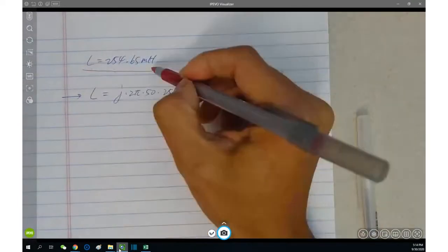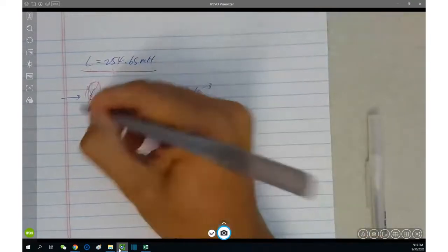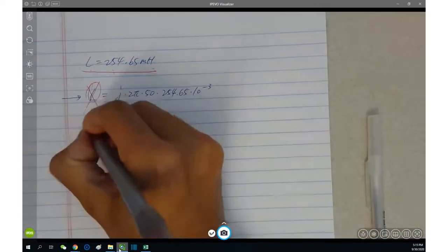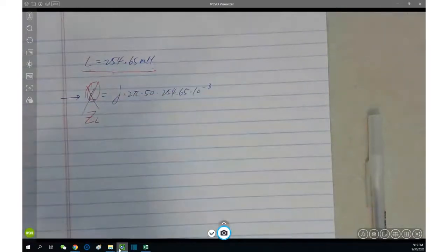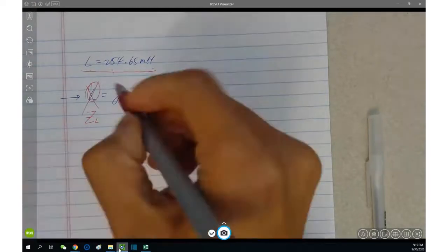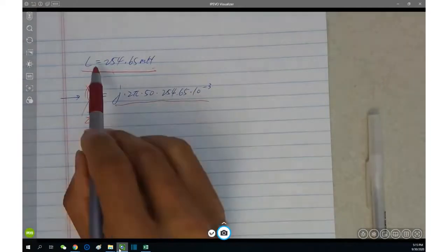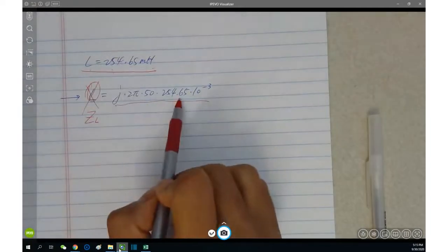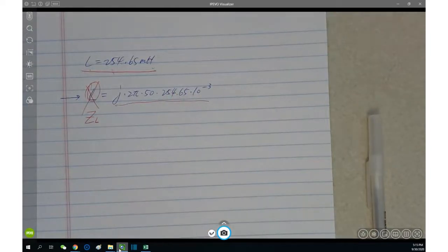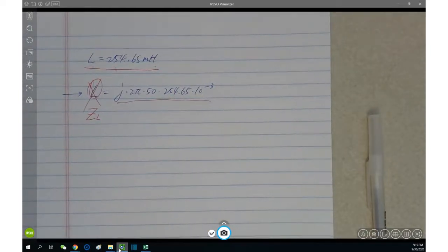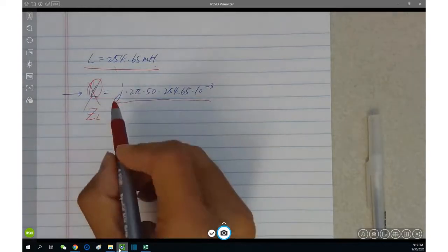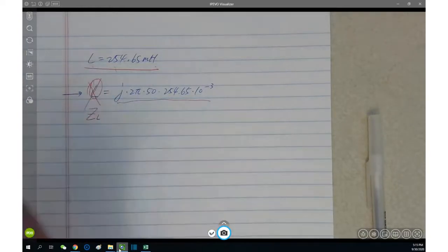You see here, the inductance is given like this. How could you have L again? This is Z sub L, the impedance of the inductance, rather than the inductance itself. You can't write L equals this. Obviously, it makes no sense. You can't have L equals this and also equals that, which is different. In terms of the concept, this is the inductance, this is impedance. Inductance is not equal to impedance. You can't do that.